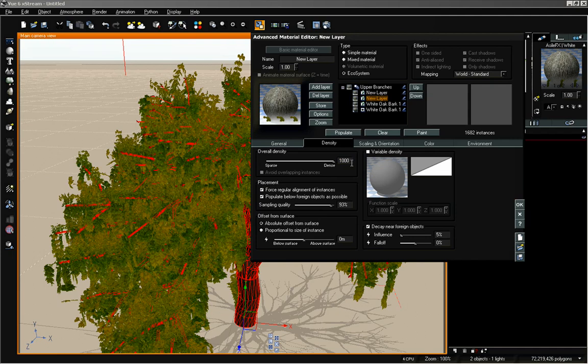And you can actually increase these values very, very high. The overall density amount, if you really want it to be concentrated, I've used values up to 500,000 and sometimes even more without crashing the viewport and not oversampling too much.